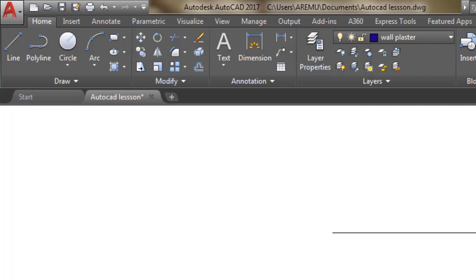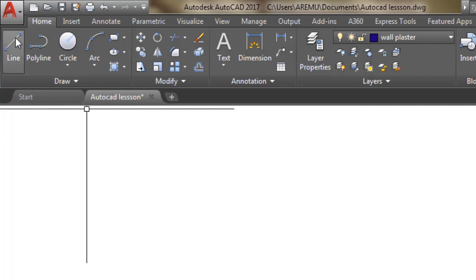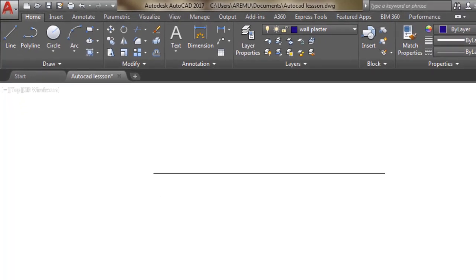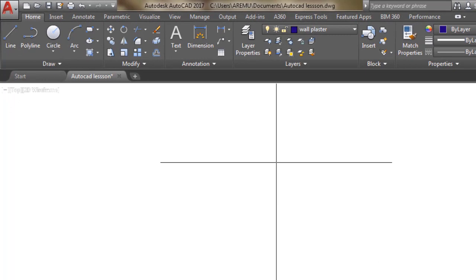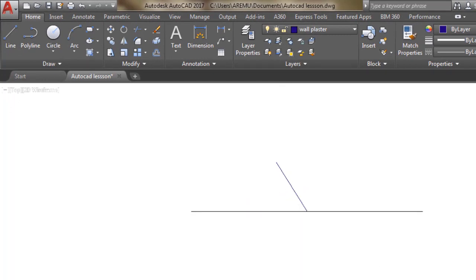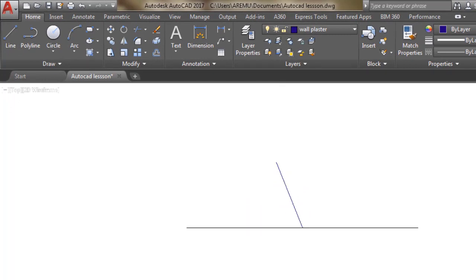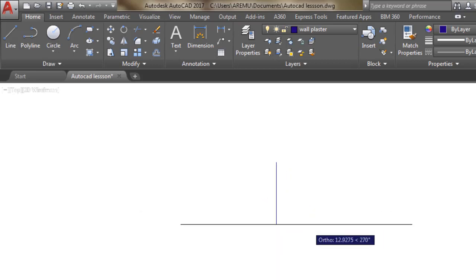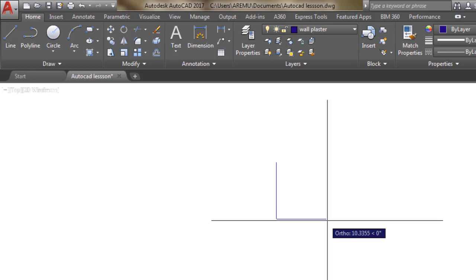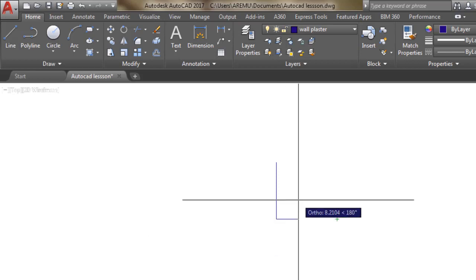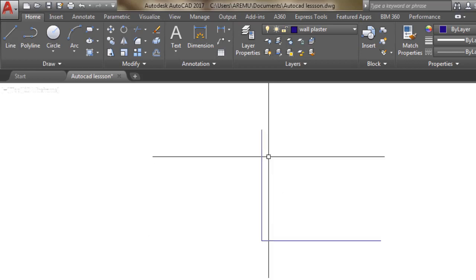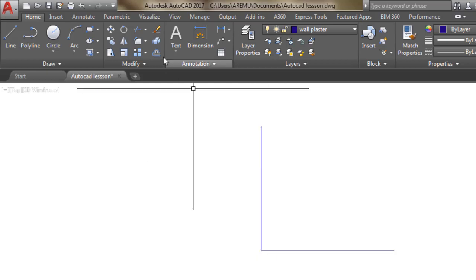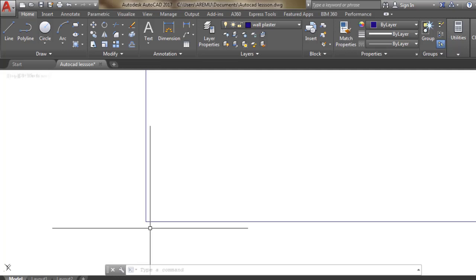From the drawing that I expected you to have printed from that floor plan, let's go to line. What we are going to draw first is an L shape. I know by now we know how to draw lines and so on, so I will not go into those details anymore. Just press F8 and draw a line. First of all, you press enter. What remains now is to offset, to give the line the walls it deserves. So you go to offset.